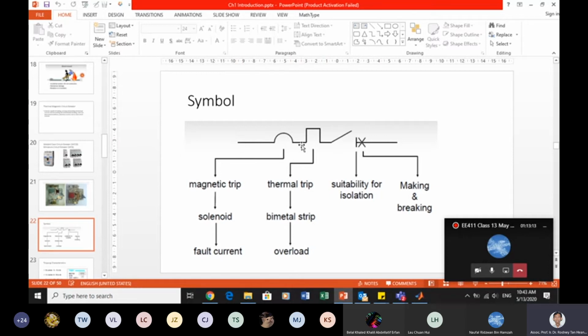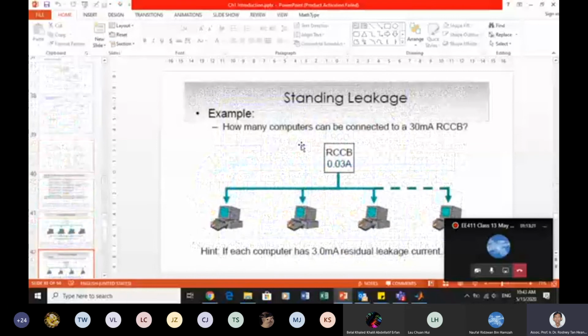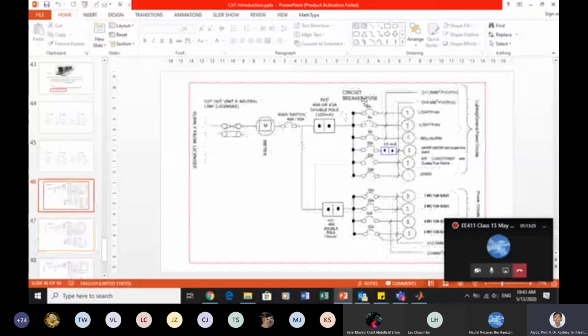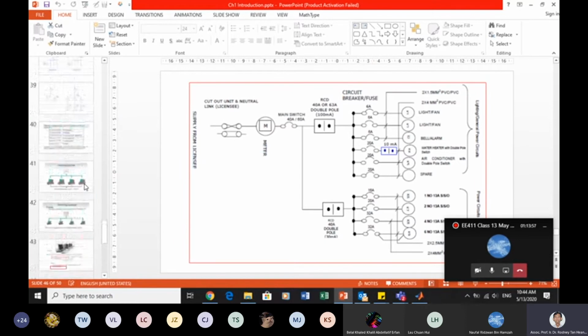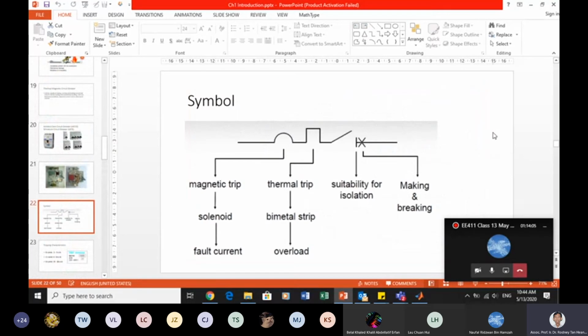Now in Malaysia, we use this. Let me just go faster. Oh, that's all IEC standard lah. Okay, in Malaysia, we use this. We call it the happy face: 2 dots and 1 like an inverted happy face. If you turn it around, it's just like a happy face, because it depends on how you draw the diagram. So this is what the Malaysian consultants and contractors use. When you draw this, the contractor can understand, oh, these are all MCB. So for the international students, you have to go back and understand what types of standards your country follows. The drawing symbols are, in other words, different.